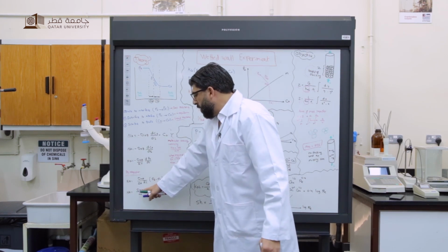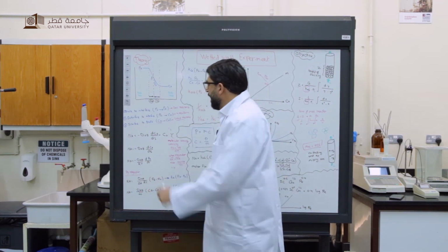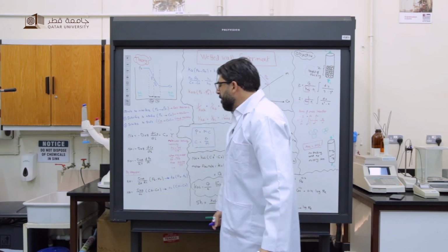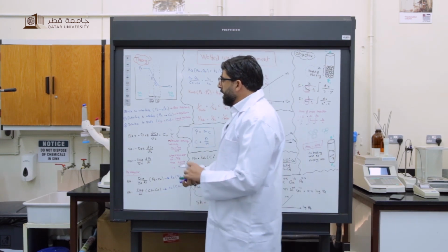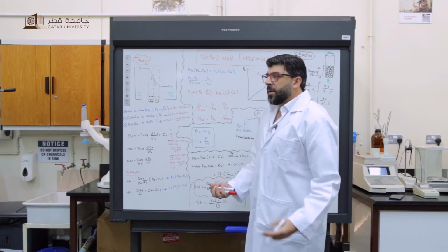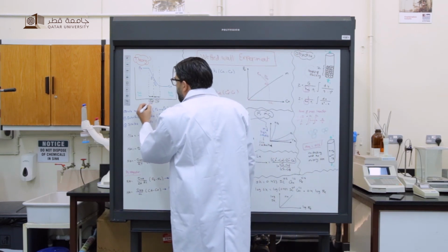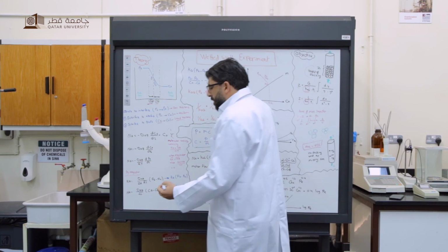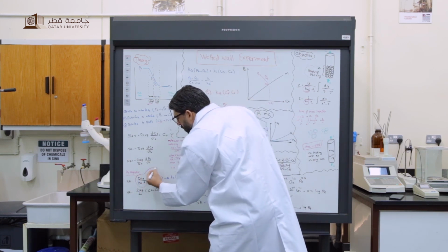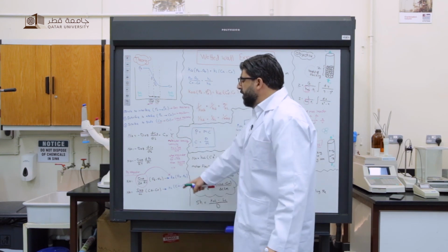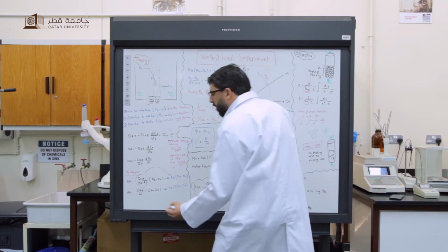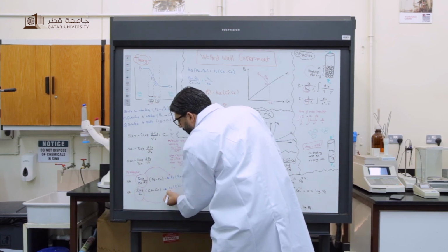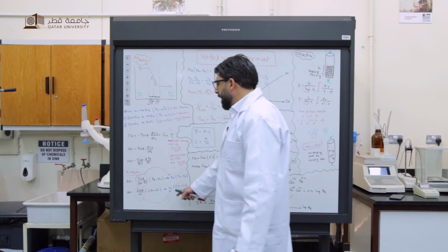It will be diffusivity from A to P, ZL, this is the ZL, and CAI to CA of the bulk. Now, there's a problem that we can't experimentally define the interface distance, ZG or the ZL. So it's difficult to determine. So now we can convert this part into KG, so it's the individual gas transfer coefficient. And also the DAB over ZL, it will be the individual mass transfer coefficient for the liquid phase.